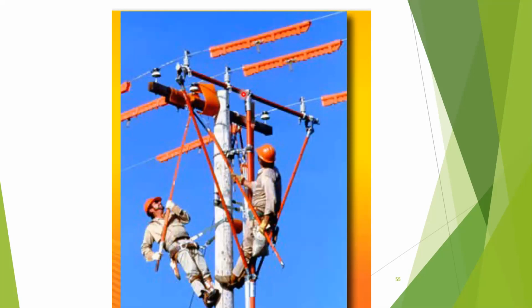What they have done is remove the binding on the insulators over here, the connections, and then they are going to lift this portion so that the conductors are lifted over the cross arm.